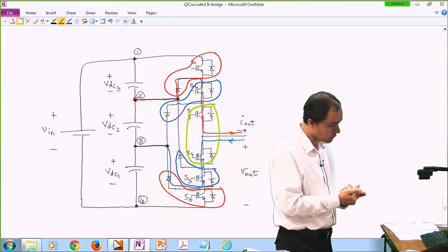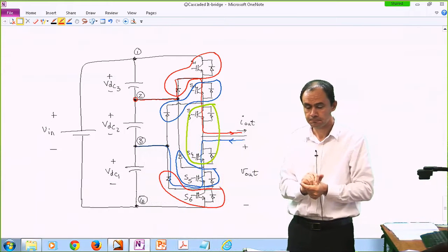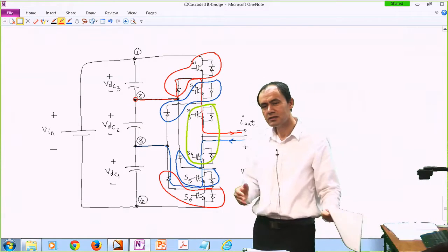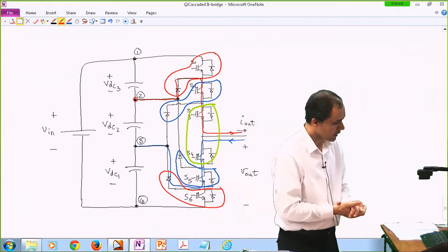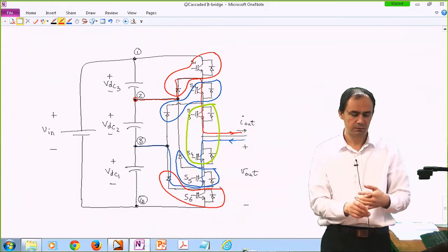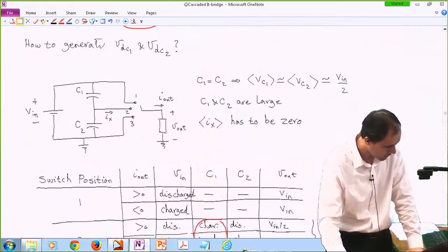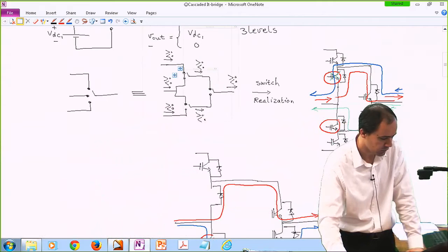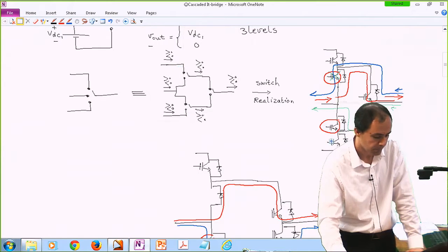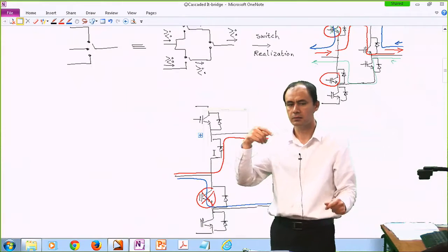All right, any questions? How do we exactly get to the conclusion which switches will complement? Oh, it's not a conclusion. This is how they have been designed, but the way it's drawn is a little bit confusing. Honestly, I can't tell you how, but going back to the way we constructed our first 3-level switch using single pole double throw switches, we put a bunch of these guys over here, and then we realized for the realization of these complementary switches, we only need a diode in the bottom, something like this.